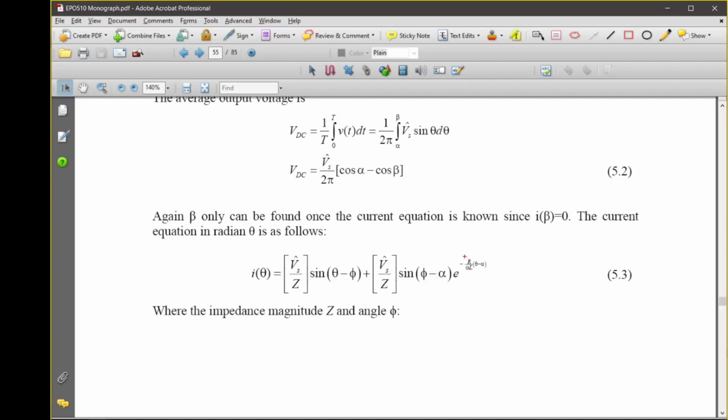And we have this R minus R over omega L. One thing I need to share with you is another variable known as the time constant. When you analyze an R-L circuit, you always need to consider this time constant. As a rule of thumb, when the circuit gets to 5 times the time constant, it has normally come into the steady state condition.